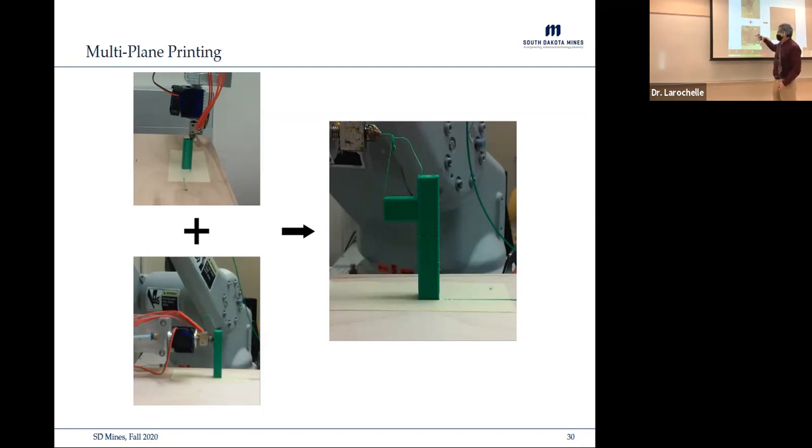So now you can see the robot is doing a build direction in this direction, as I'm pointing here, and layers are being built and cantilevered, hanging in midair, no support structure, nothing. Hopefully you can see it online better than how washed out it is here, but we've got this cantilevered section, which is just printed in free-form additive manufacturing. Again, with no support structures or anything, and it doesn't creep, it doesn't droop. The material goes where we want it to, and it stays there.